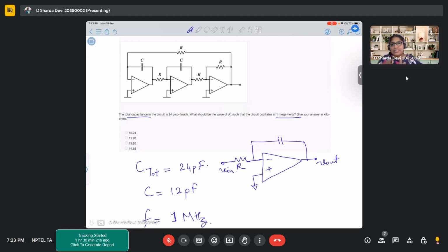It is where you see the C's. This one cannot give you frequency components. Ideally, we don't consider op-amp internal capacitors. Since there is no external capacitor, you don't have to care about this term, as it will not introduce any capacitive or frequency dependent term.